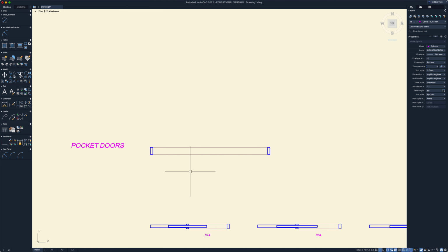So all we're going to do is just create a line starting from that point, going back 2,140, and then we're going to go over to the right, and it's easiest just to touch that point down there, don't click, and then if I slide up, you see it makes that green little line there and will snap into position, so I don't even have to type anything in. Otherwise you could type in the width, which was 2440. Okay, and then we're going to go back down to this point.